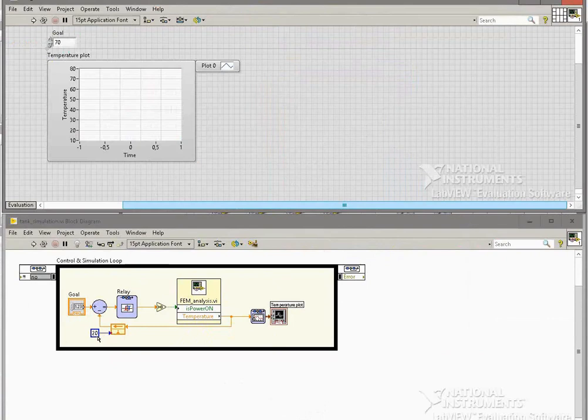"20" is the initial temperature to initialize the feedback. These blocks subtract temperatures and we get the temperature difference between the desired temperature and the actual temperature. Then we have the relay block.